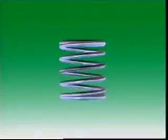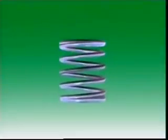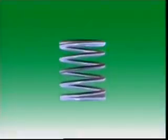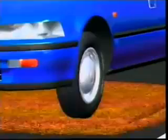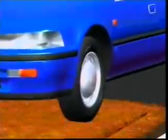When a vehicle strikes an uneven surface, the springs are deformed from their original shape. They return to their original position but tend to overshoot and set up oscillations. This makes the vehicle bounce up and down, which makes the ride uncomfortable. It can produce forces that make the tyres bounce, and a bouncing tyre won't grip the road surface well.